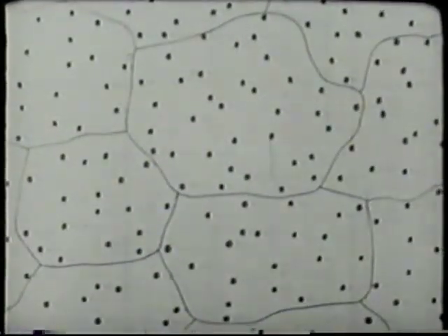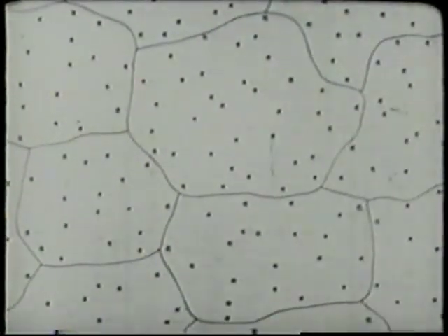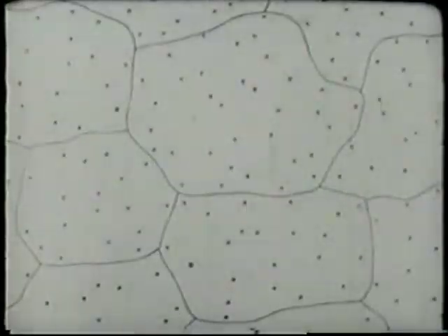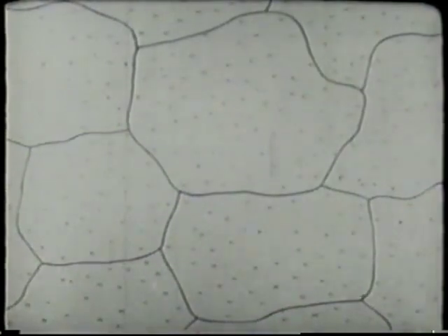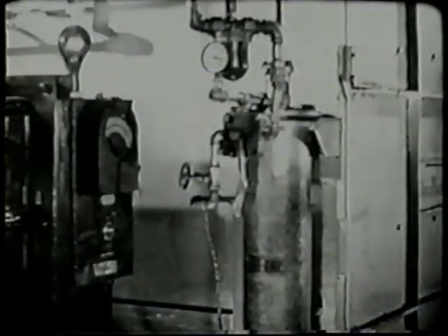The two essential characteristics of an air furnace are rapid circulation of air and controlled heat. These are achieved by forcing heated air among the parts and maintaining nearly uniform temperature by controlling the heating elements. During the soaking period, the microstructure of the metal is altered, the CuAl2 particles growing smaller as the copper goes into solid solution with the aluminum.